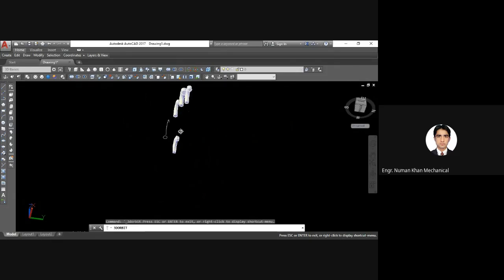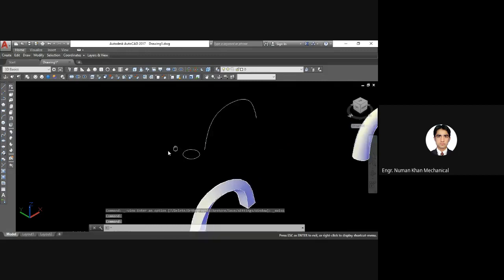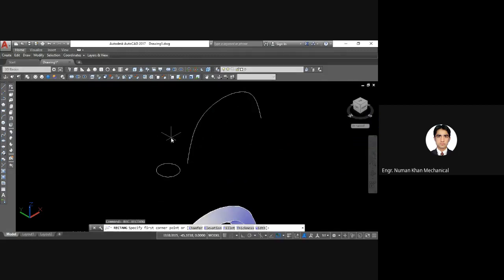You can apply twist and scale simultaneously. I mean that, let's say, let me draw another rectangle over here, then you will see what it means. Let's say there is a small rectangle over here, and I want to convert this using the sweep command. Sweep, select object, okay. Let me apply a twist angle, which is 90 degrees. You can give any, and let me give a scale as well. It is 1.5. Now select the object.